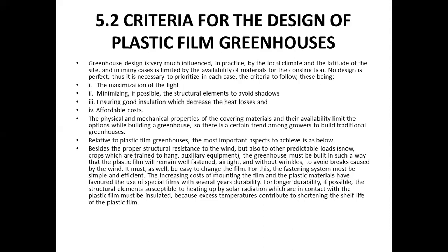The increasing cost of mounting the film and plastic materials have favored the use of special films with several years of durability. For longer durability, if possible, the structural elements susceptible to heating up by solar radiation which are in contact with the plastic film must be insulated, because excess temperatures contribute to shortening the shelf life of the plastic film.